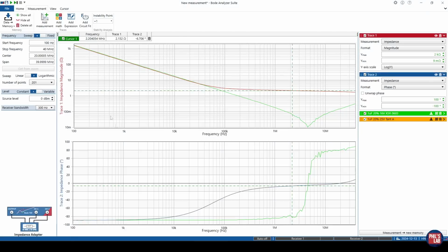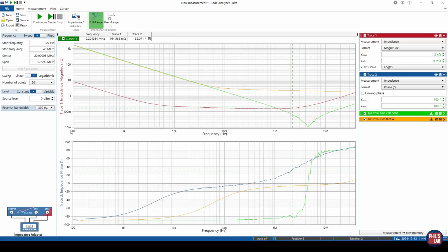Going back to our measurement setup, measurement window, we'll go to home and start a new measurement with this capacitor now in place. Now the red curve is our latest measurement, yellow is the tantalum, green is the multilayer ceramic. And this is very much what we can expect. Our initial impedance profile is much lower, so the magnitude of the impedance in the low frequency range, because of the far larger capacitance compared to 220 microfarads to 1 microfarad, our impedance is going to be much lower for